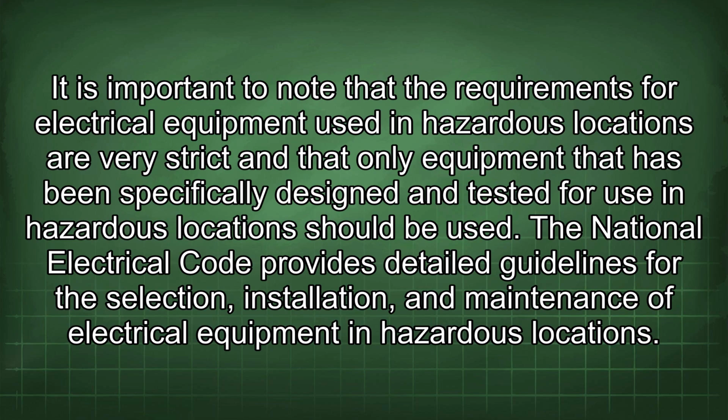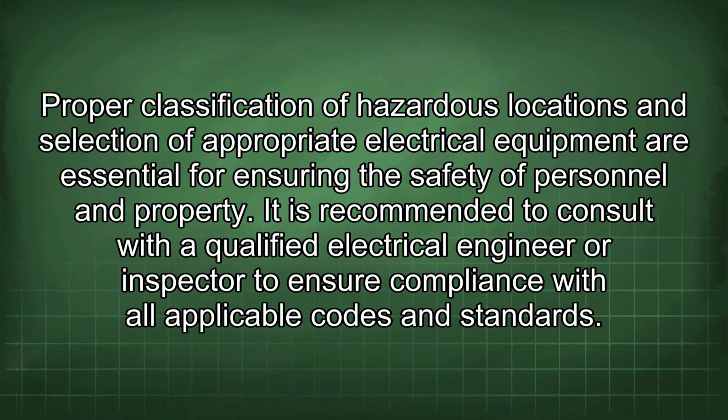It is important to note that the requirements for electrical equipment used in hazardous locations are very strict, and that only equipment that has been specifically designed and tested for use in hazardous locations should be used. The National Electrical Code provides detailed guidelines for the selection, installation, and maintenance of electrical equipment in hazardous locations. Proper classification of hazardous locations and selection of appropriate electrical equipment are essential for ensuring the safety of personnel and property. It is recommended to consult with a qualified electrical engineer or inspector to ensure compliance with all applicable codes